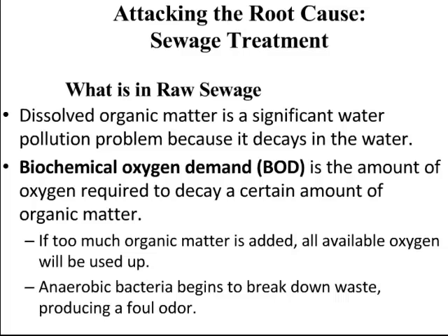Now, when we're trying to measure what that pollutant is, the Clean Water Act will actually tell us these are the specific criterion pollutants that are listed. And I'm not going to go through and do all of them because there's just physically too many chemicals listed. But the one we'll talk about the most is this idea of BOD, biochemical oxygen demand, sometimes called biological oxygen demand.